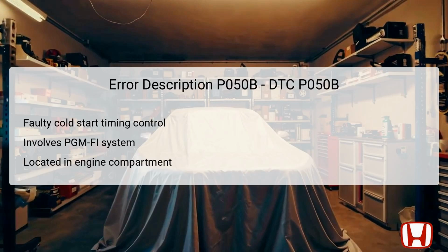The DTC P050B relates specifically to a malfunction in the cold start ignition timing control system. This system is part of the PGM-FI, or Programmed Fuel Injection System, responsible for regulating the fuel supply and ignition timing to optimize engine performance, particularly during cold starts.